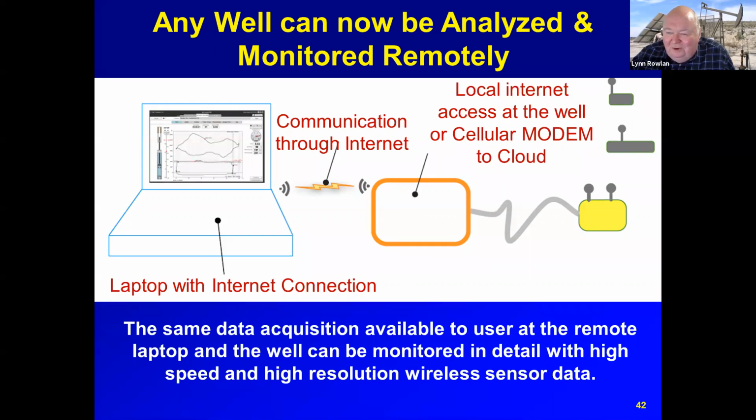So a deviation survey is important if you're trying to calculate pressure. If you have a horizontal well, you need to not be surprised that you can shoot past the end of the tubing if it's a gas well or a well that would be flowing, because the liquid will segregate.